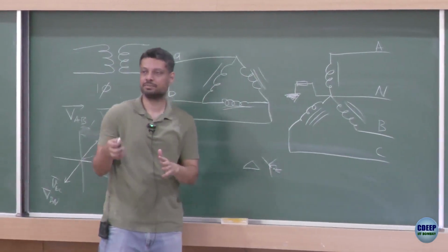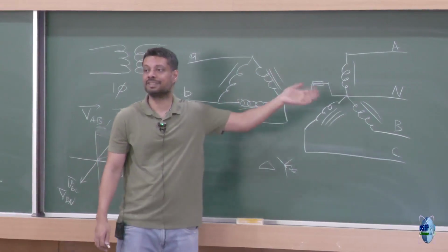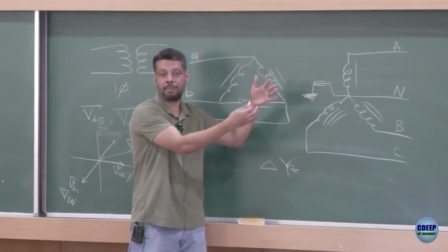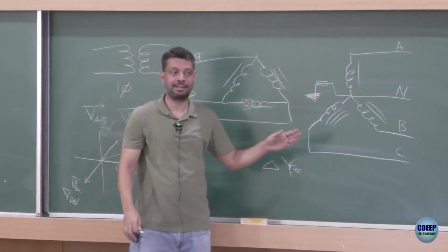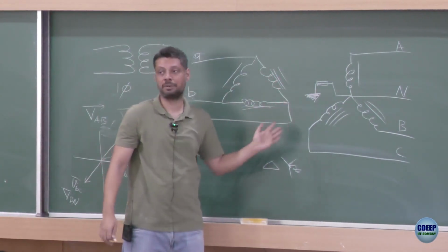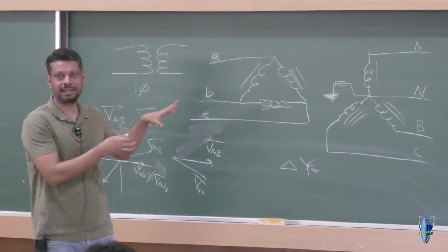Only place where it does matter is, what if you have these 3 transformers and the output of the 3 transformers are then connected in parallel to feed a bigger load, right. Then all 3 of them should be star delta. You cannot do like one delta delta and one star delta, because then there will be a big problem, right. Just looking at one transformer, there is no problem.